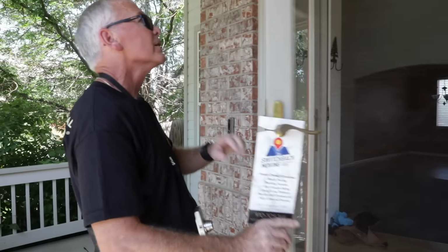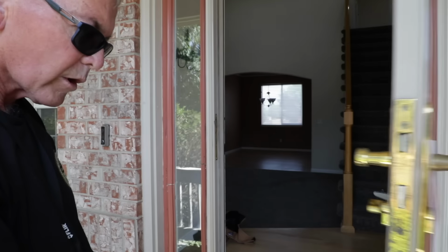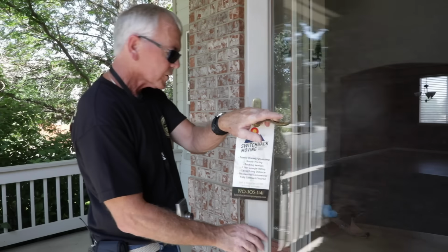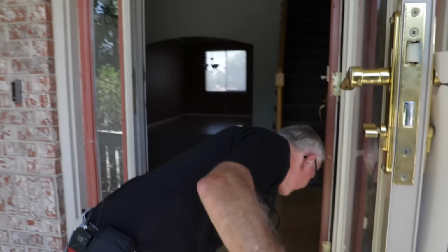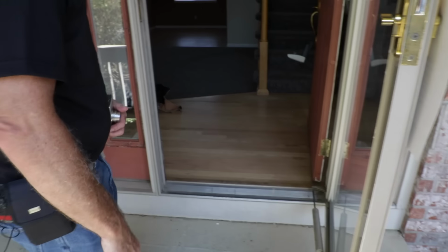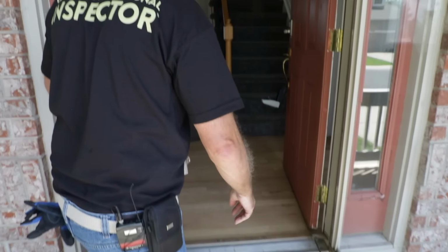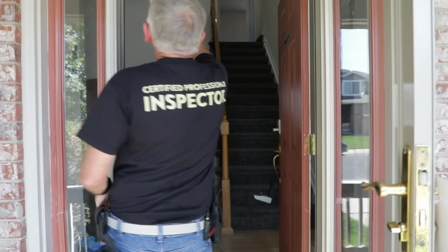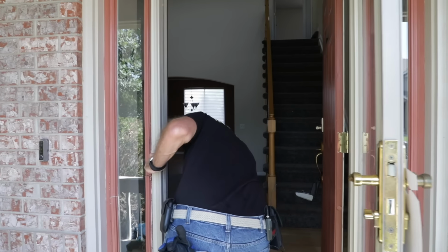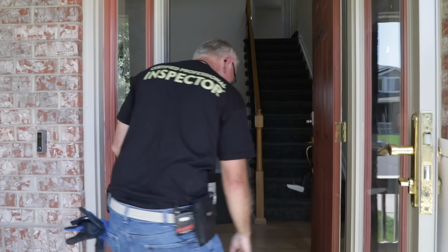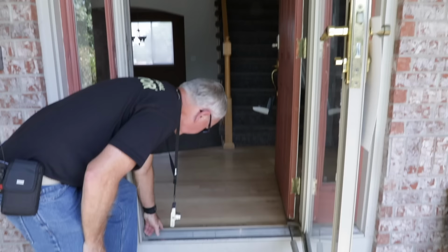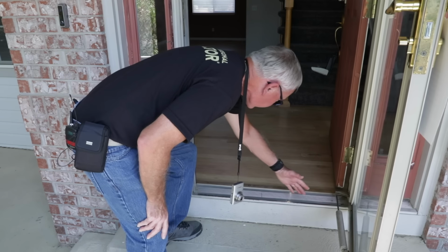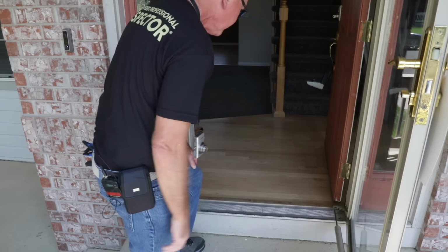Now I'm going to check this storm door. Check the closing device, and it closes and it latches. Now I'm going to move in here to the inner door. I'm going to check all my weather stripping all around the jamb. Those are all in pretty good shape. Check the threshold. Make sure that I don't have any open holes or screws that are drilled into this outer part of the threshold, which would allow water to get in.